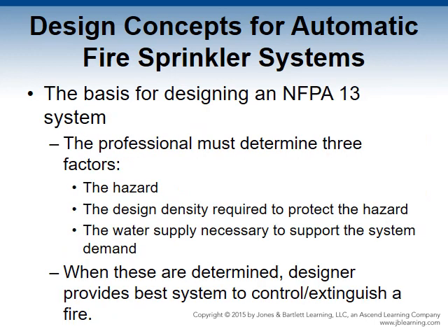The basis for the design of an NFPA 13 system is as follows. The professional must determine these factors before the design can be moved forward: the hazard, the design density required to protect the hazard, the water supply necessary to support the system demand, and when these are determined, the designer will provide the best system to control or extinguish the fire.